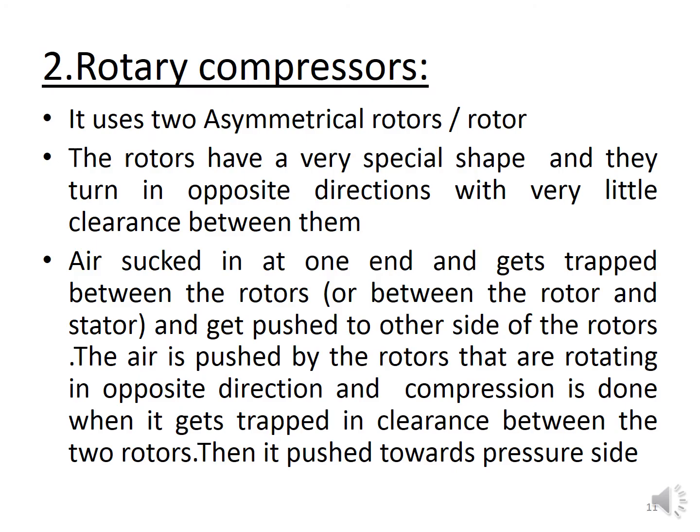Okay. Now rotary compressors. It uses two asymmetrical rotors or a rotor. So now what is asymmetrical? That means not similar. Like half is different and half is different. Like two rotors. They are different in sizes or shape. The rotors have very special shape and they turn in opposite direction with very little clearance in between them.